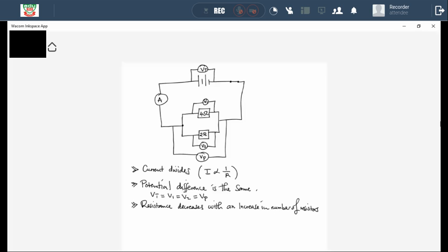And what effect does it have? Remember, we said whenever resistance decreases, current goes up because current and resistance are inversely proportional. So in our exam, they might not ask you a straightforward question like, if we add a resistor in parallel, what happens to the total resistance? No, they won't ask you about resistance. They will ask you about current. If we add another resistor R3 to this parallel circuit, what will happen to the total current of the circuit? That will be the question that they would be interested in.